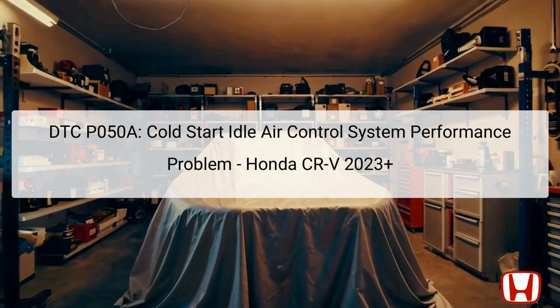Welcome to the troubleshooting guide for DTC P050A, which stands for Cold Start Idle Air Control System Performance Problem, specifically for the Honda CR-V from 2023 onwards. This error is primarily related to the Powertrain Control Module, PCM, which is responsible for regulating airflow in relation to the target airflow during the quick warm-up system, QWS, operation. When the actual airflow deviates, either being insufficient or excessive, the PCM identifies this anomaly and accordingly stores the DTC.